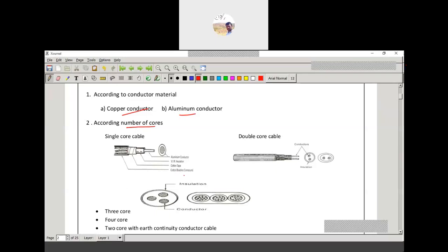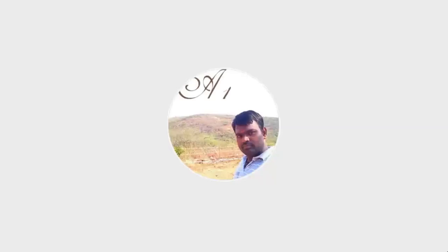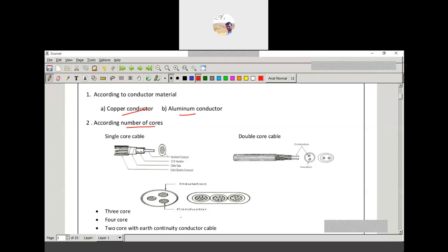It will protect the equipment from overload and current above the rated values. The operation is the same as an MCB, but it handles above-rated current values. The available current ratings range from low, such as 15 amperes, to industrial ratings such as 2500 amperes. So we can use it for low to high applications.